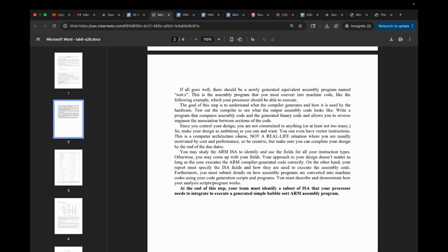As I specified earlier, we went with the official ARM ISA, and we were able to implement a good amount of functions, like almost all the widely used R-type and I-type instructions, LDR and STR, which load data to the register and store data from the register to the memory, load word, store word instructions, and all the control flow statements, like the conditional branch statements: branch if equal, BGE, BLT, and also unconditional branch, and jump and link, which is branch and link in this particular ISA.